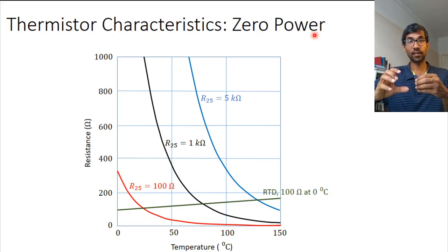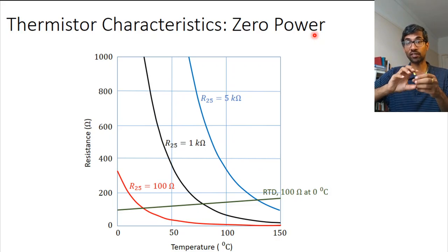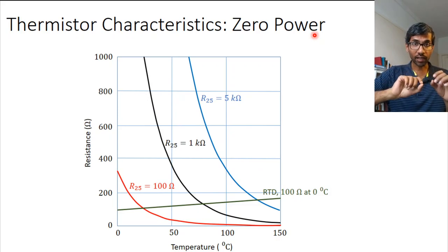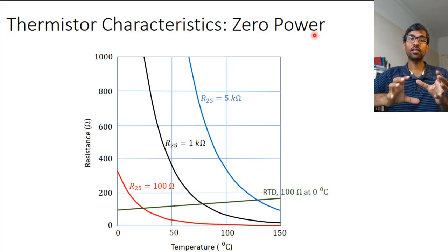the resistor. Now, if it is a thermistor that is measuring the temperature of the environment, then you have power dissipation because of the current that is increasing the temperature of the thermistor, and the environment that is influencing the temperature of the thermistor. Okay. If you keep your current very, very low, you can almost ignore the power dissipation and its contribution to the temperature of the thermistor.